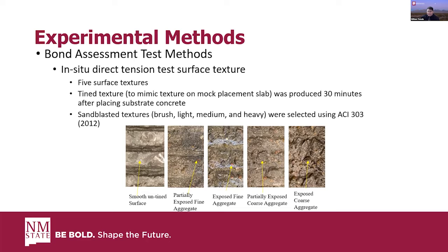So the brush sandblasted texture partially exposes fine aggregate, and the light sandblasted texture exposes fine aggregate, and the medium sandblasted texture partially exposes coarse aggregate, and the heavy sandblasted texture exposes coarse aggregate.